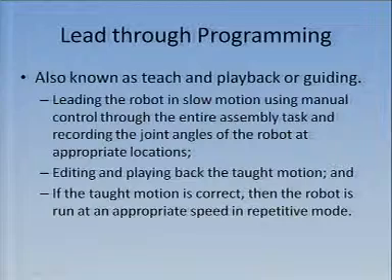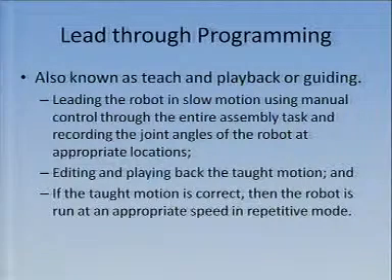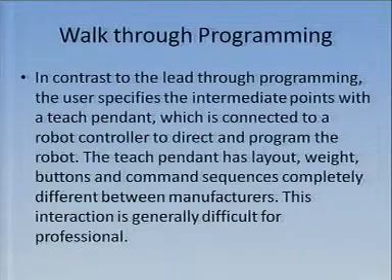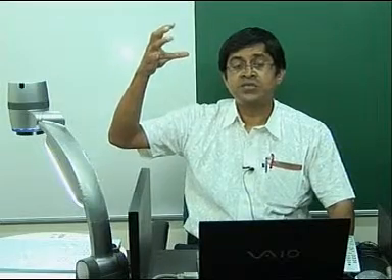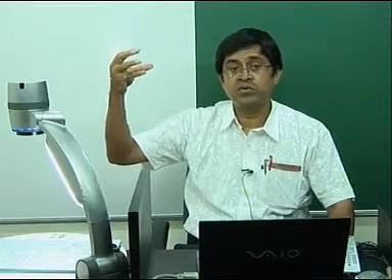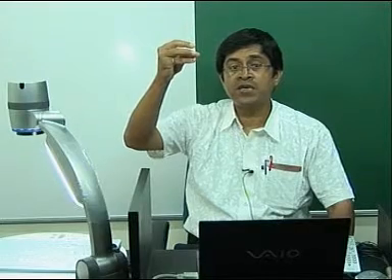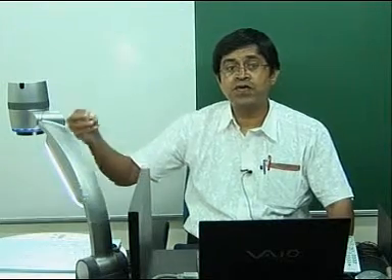So, here again we can classify this as lead through programming. That means you guide and playback the way I have said it, and then we have walk through programming. Walk through programming is like this. Again, look at my hand. Suppose lead through is I go slowly to every point. Walk through is I take the points here and I take it to the next point.